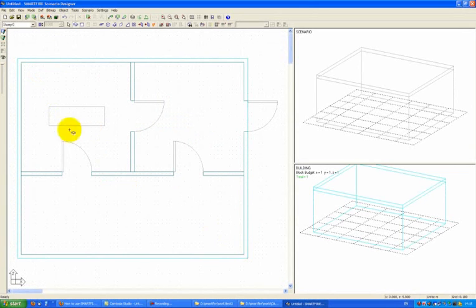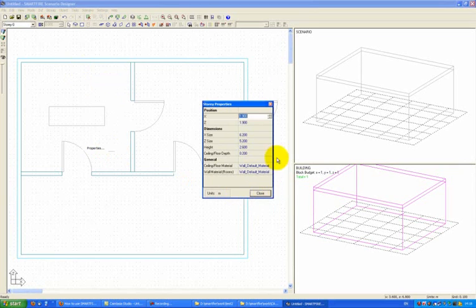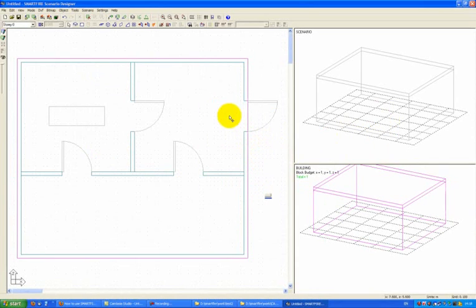So we select, drag and select again to define the outer limits of the story, and at this stage it's worth checking the story height is correct, because that information usually doesn't come through the DXF file. In this case I'll accept the default of 2.6 meters high and the default ceiling depth of 0.2 meters.